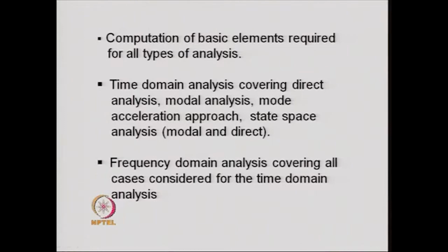The first segment consists of computation of basic elements required for all types of analysis. For example, you have to obtain the overall stiffness matrix, then the condensed stiffness matrix, then from the condensed stiffness matrix the non-support degrees of freedom and support degrees of freedom matrices are isolated, then coupling matrices are considered.